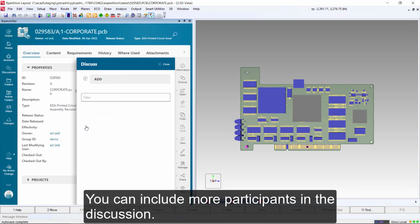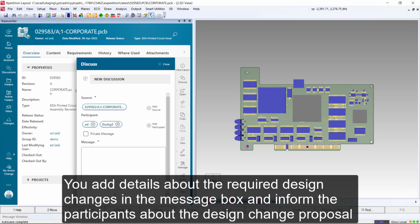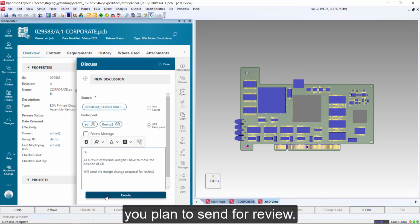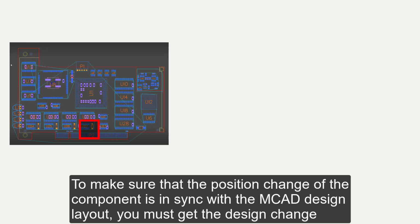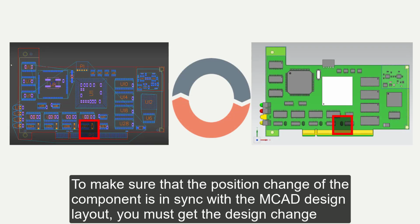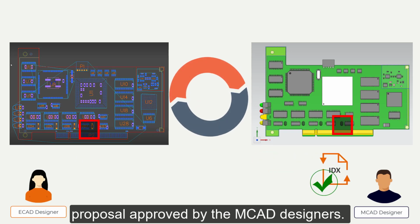You can include more participants in the discussion. You add details about the required design changes in the message box and inform the participants about the design change proposal you plan to send for review. Next, you send the message to the associated MCAD designer. To make sure that the position change of the component is in sync with the MCAD design layout, you must get the design change proposal approved by the MCAD designers.